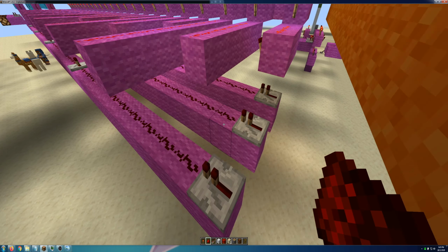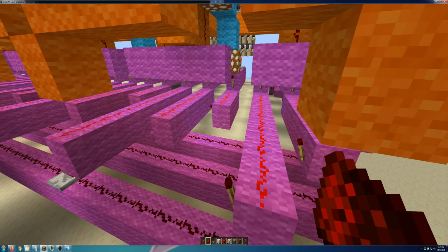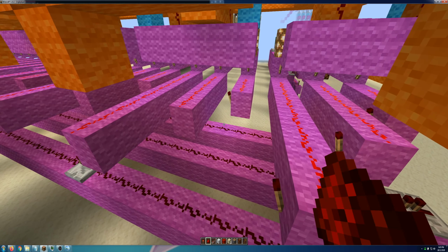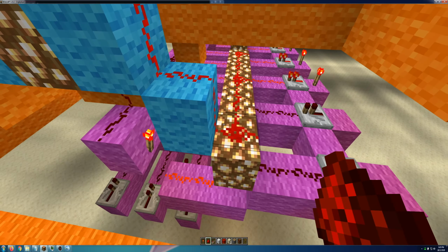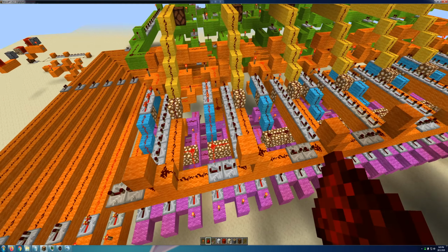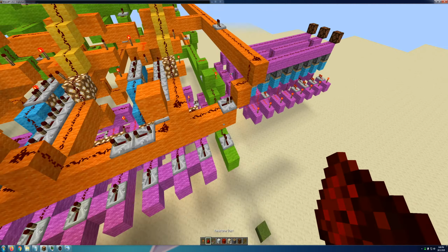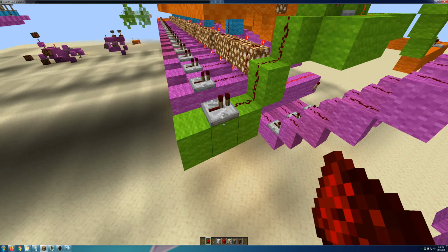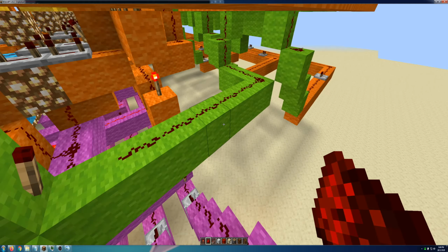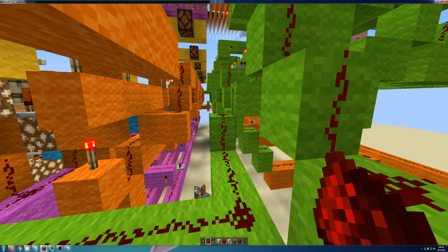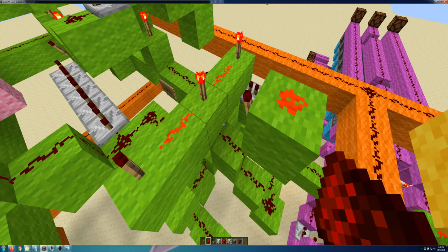So in this case, we have the signal bus for the colors, and each line for each column is correlated to go down. However, that is being prevented by this glowstone line. If we move over to the right, we have the on button, which is sort of the thing that initializes it. So as this on button turns on, it just creates a small pulse, and all the small pulse does is we have this AND gate here.